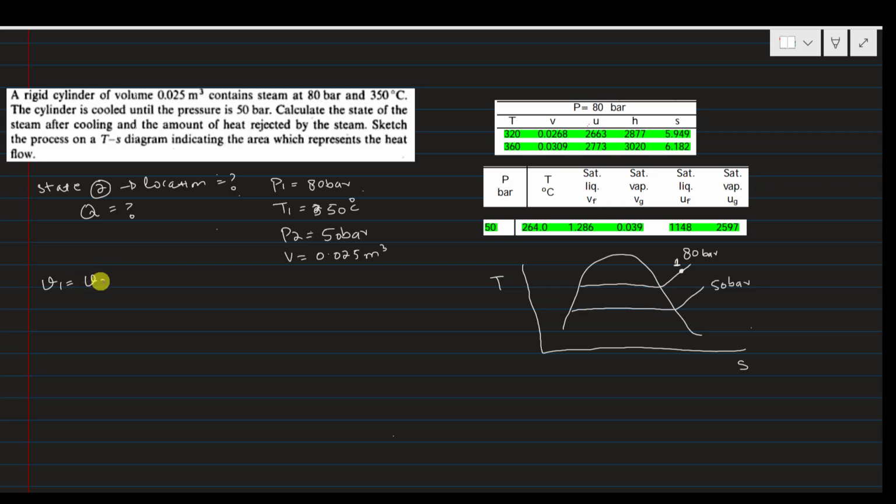So that is V equals VA plus VB minus VA divided by the temperature difference, TB minus TA, into T1 minus TA, where T1 is the temperature at which you are finding the specific volume. Remember, the values of the specific volume VA and VB, and of TA and TB, you can get from the superheated steam table. Here I have extracted the portion of it. This is the TA value, this is the TB value.